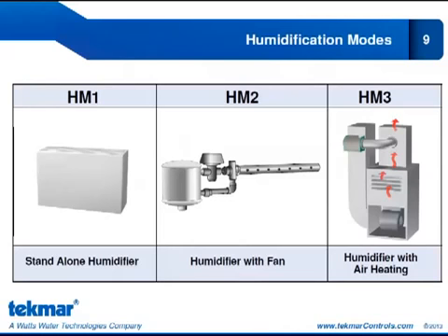There are 3 humidification modes in the 553. These are the same modes that are in the 557. Humidification mode 1 will enable a standalone humidifier. So this is a piece of equipment that is not in the ductwork. Humidification mode 2 is a humidifier that will require a fan for operation.